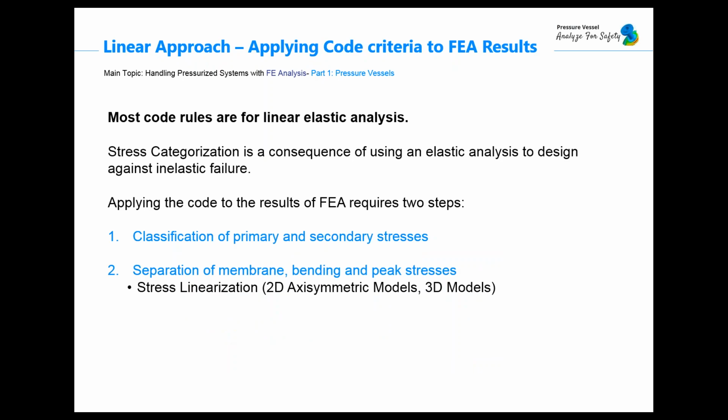But for FEA, the situation is not so easy in terms of classification for the stress limits, and depending on the element type, any kind of finite element software provides different result data. And for a two-dimensional element, which is recognized as shell or plate, depending on the code, results such as membrane and bending stresses are obtained directly and they are compatible with the code requirements.